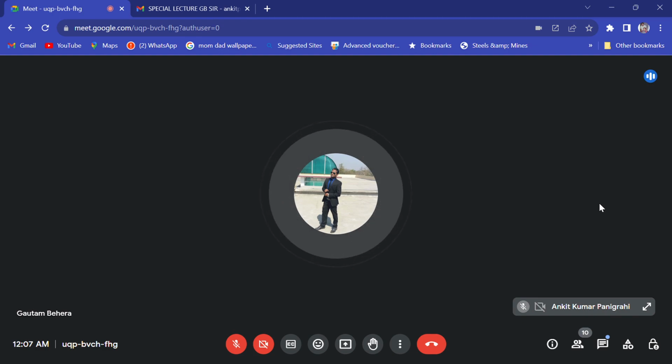Here in blast furnace, what happens? The material is moving from top to bottom. But in rotary furnace, the hearth is rotating. It is rotating the raw materials from one place to another. The raw material is not moving, right? So in this way, you can use fines. That is the advantage of it.